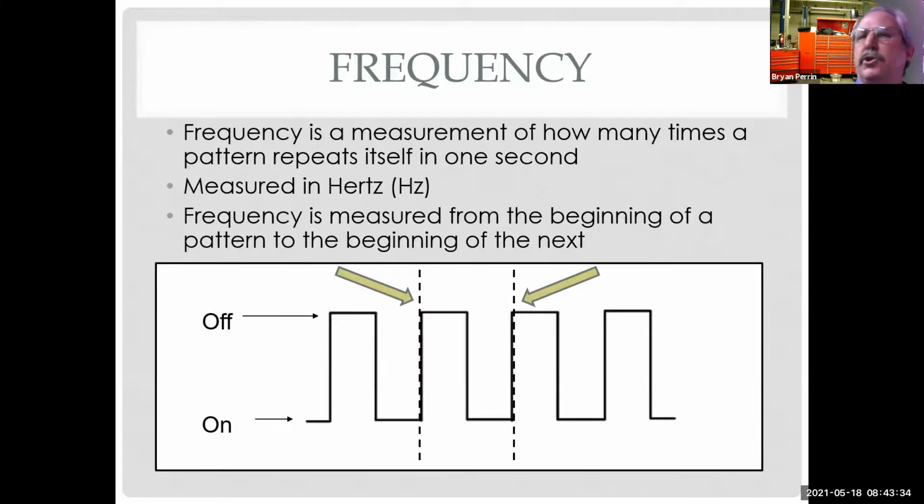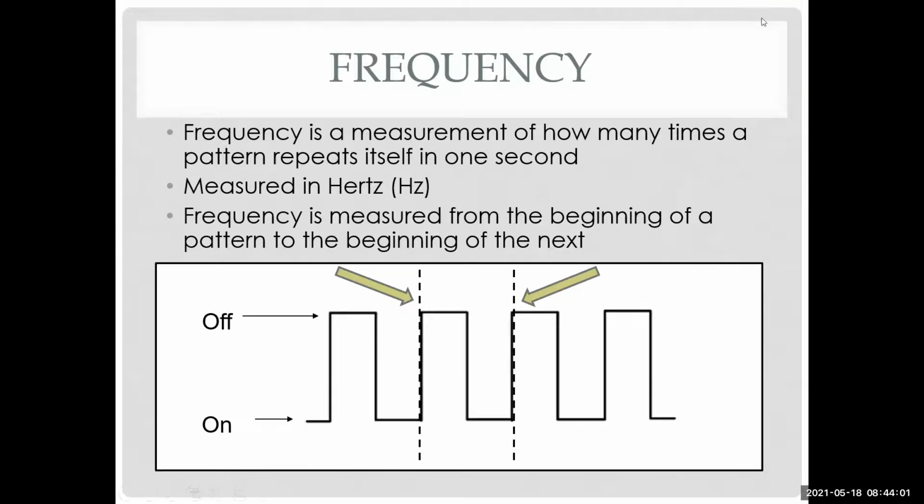So that's another cheap way I might use a digital multimeter, if I have a higher end one that does frequency, to test something I should really have a scope for. I could hook it up and see: does it make a frequency? Does the frequency change? So I could test a permanent magnet sensor that way with a meter on frequency, because we know the frequency changes with speed. Okay, thank you. You bet.